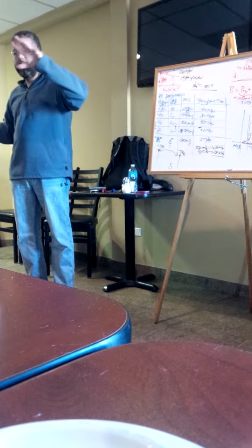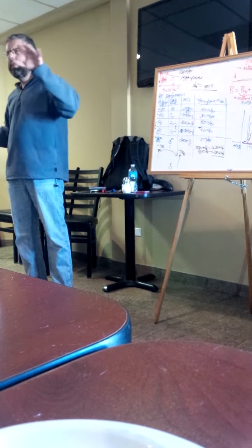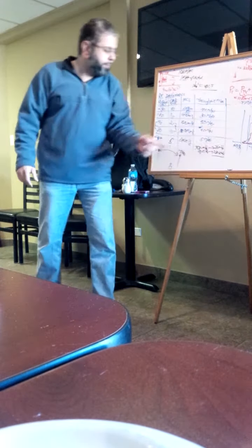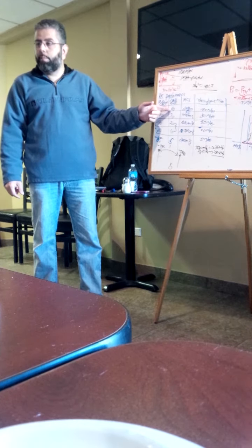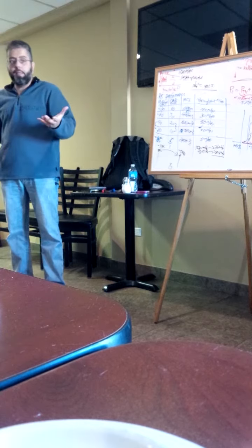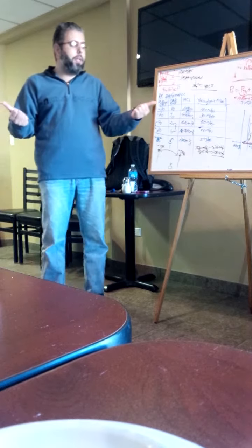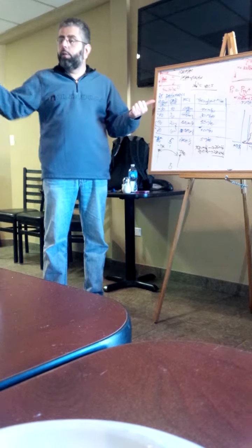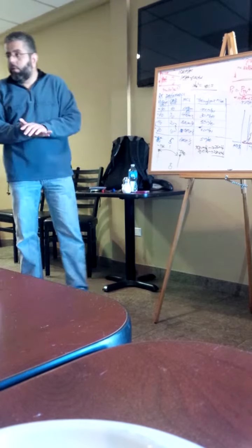So I know that on all these other frequencies, hey, I can hear him at minus 50, I hear him at minus 80, I hear this frequency at minus 90. The one with the best signals, the guy at minus 90, I'm going to also transmit at minus 90. Because if the floor is at minus 90, then if I'm at minus 50, I've got 40 dB of signal to noise ratio. You get it? So if somebody hears the floor at minus 90, and he knows he could receive a guy right next to him at minus 50, he's going to choose that one, because the next lowest guy on that same frequency was at minus 90, so he's going to have a really good signal to noise ratio.